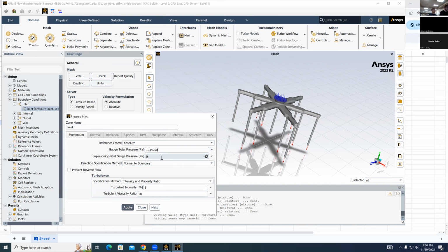And we're gonna have 5% turbulence. This is all fine. This is standard. This is not a super high accuracy CFD. We could make it more accurate. We could have the right turbulence, the right supersonic, whatnot. But because this is water at 150 PSI, it's just not a super complex thing. When we run it for a real hot fire, it will definitely be more complex and need to be more accurate. That will be covered probably in that class.